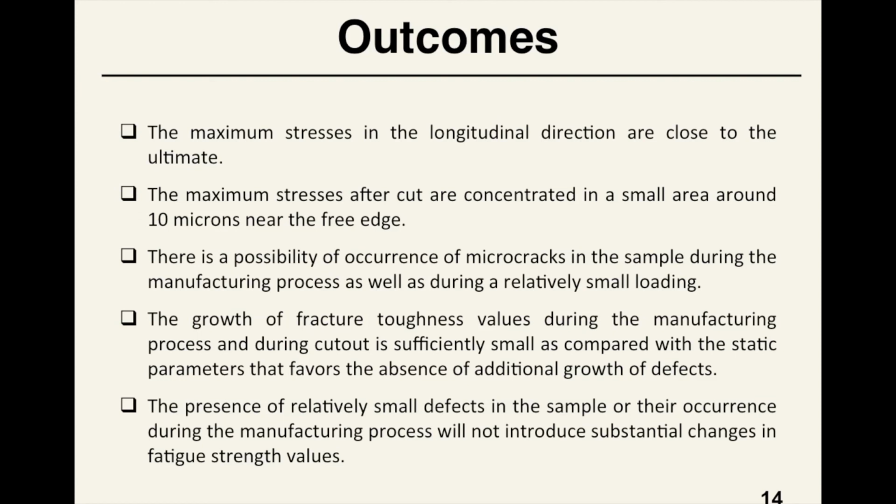The growth of fracture toughness values during the manufacturing process and during cutout is sufficiently small as compared with the static parameters, which favors the absence of additional growth of defects. The presence of relatively small defects in the sample or their occurrence during the manufacturing process will not introduce substantial changes in fatigue strength values. The values for stress components obtained by modeling are essential and cannot be ignored in subsequent structural analysis. The results of the study can be applied for prediction of residual stresses in composite structures by means of simulation and further understanding of the nature of fracture of composites.